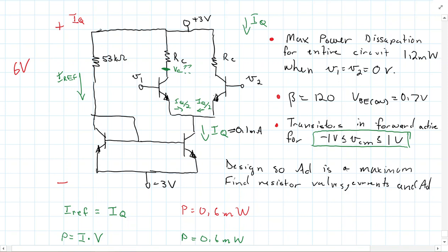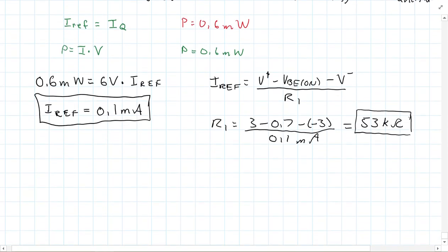Well, what do we have here? Well, remember that, of course, we have to have this junction forward biased at 0.7 volts. And that will just happen with our current mirror setting up. As long as we have everything set up properly, that will just naturally occur for us. But then what do we need here for this junction here? And so remember, this is the base collector junction. And this is where we have to remember back here.